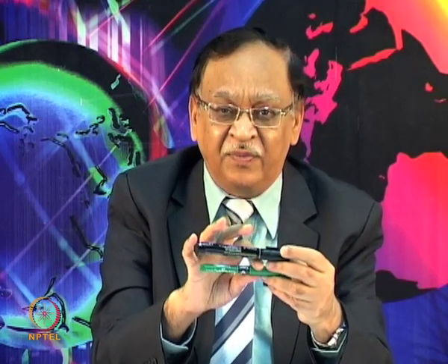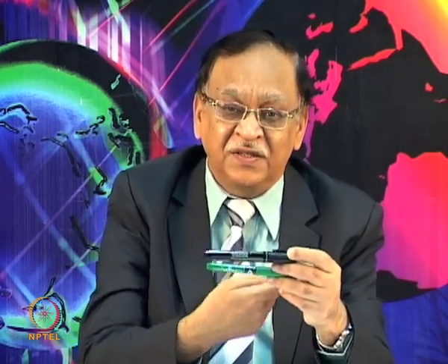Now, that has application. For example, let us say if I am transmitting say 20 watt of power, and we want to really know whether it is exactly 20 watt or it is less or more. So, suppose we have designed a 10 dB coupler, then 10 dB coupler would mean 10% power. So, that means out of that 20 watt, 2 watt will be getting coupled over here, but that is too high. So, that is why a 20 dB coupler would mean 1% power is coming here, and that can be used to monitor the power, or it may be used for automatic gain control, or this may be going